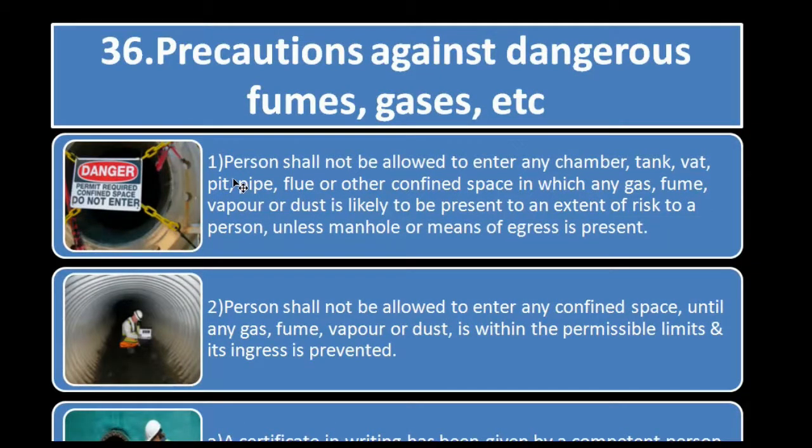Subsection 1. A person shall not be allowed to enter any chamber, tank, vat, pit, pipe, flue or other confined space in which any gas, fume, vapor or dust is likely to be present to an extent of a risk to a person, unless a manhole or means of egress is present.